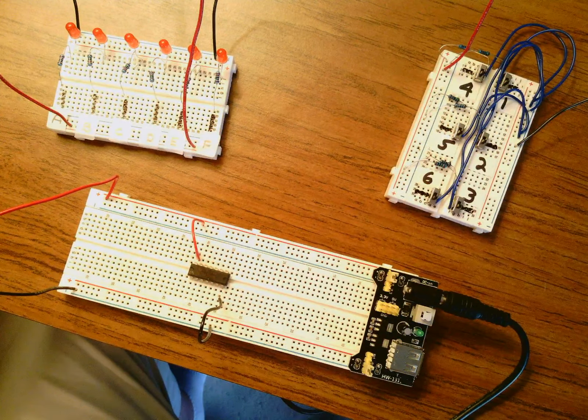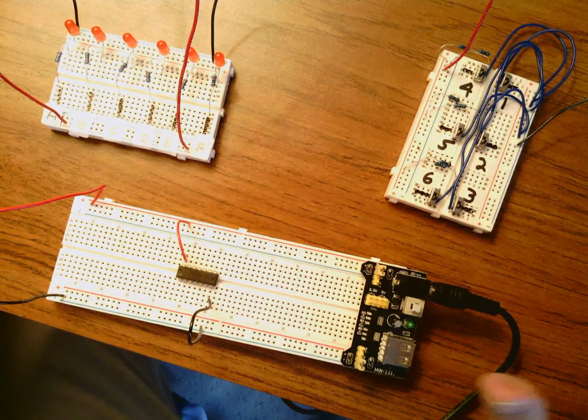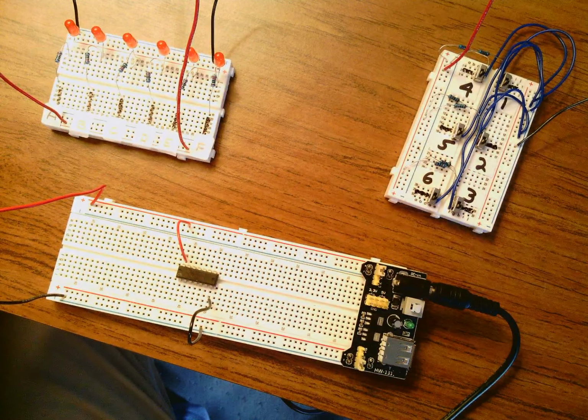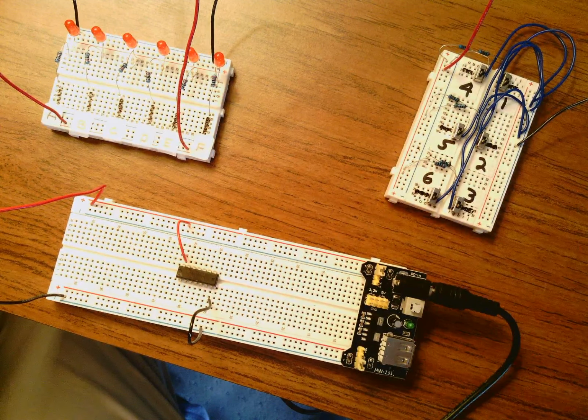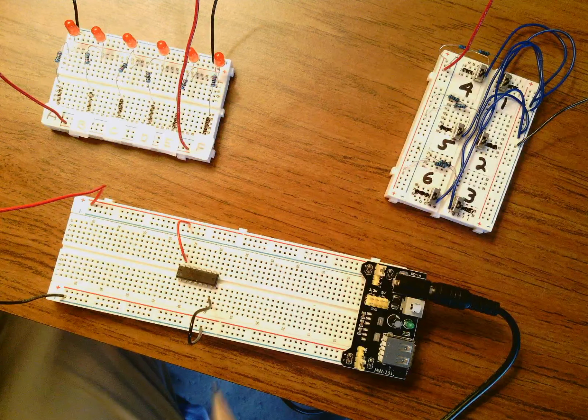It'll be ready to go. It'll be functional. What you're going to have to do in all your labs starting next week is put your chips in, get your boards laid out like this, get them tied together electrically, and get your chips biased up. I didn't use any white wire. I didn't use any green, any purple. I just used red wire for VCC, and I used black wire for ground. I always want you to use red wire for VCC. I provided it to you. And I want you to use black wire or blue wire. You can use blue or black to signify ground.